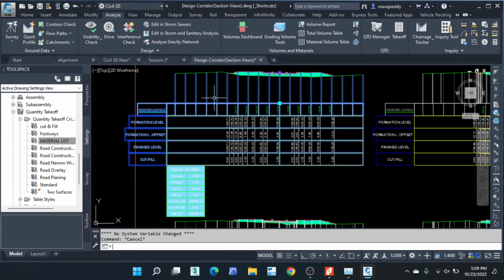So it has brought my profiles for the prime profile. Then after, I'm going to edit them. I select one of them, and I go to profile view properties. Then I scroll to the bands. I set my profile one to the vertical. The design profile is vertical alignment. Name my profile to the existing ground.